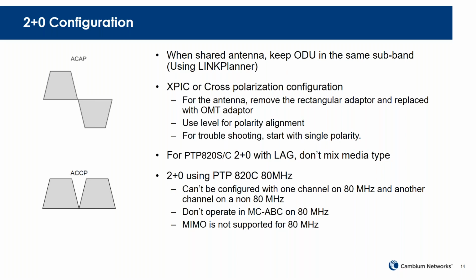I got a call from one of the customers, and he was having trouble getting the XPIC to work right. I said, okay, just go buy a level and use it for your cross-pole alignment. And he did it, and it's actually pretty quick. It's very quick.